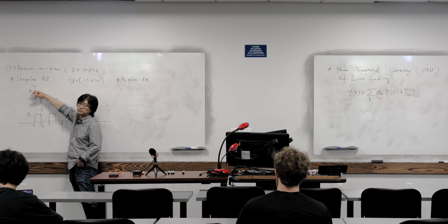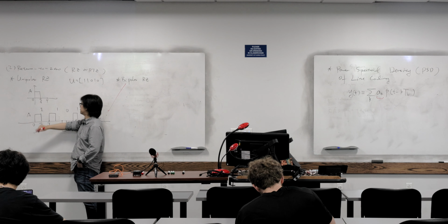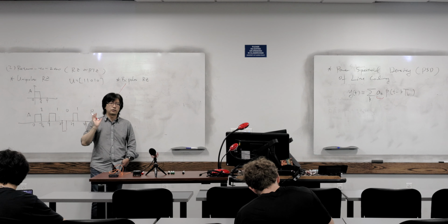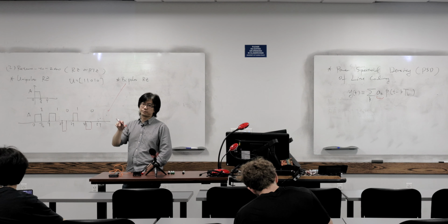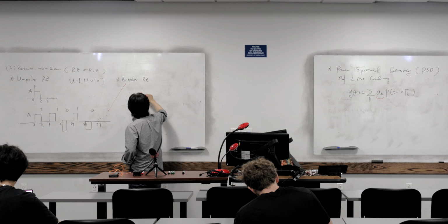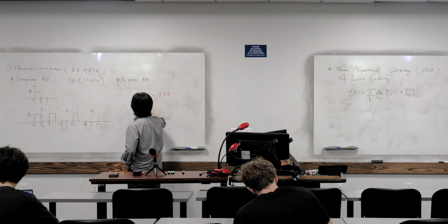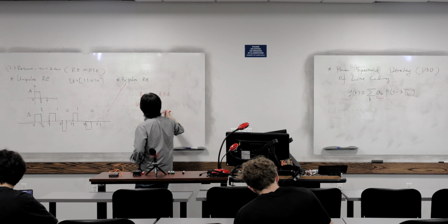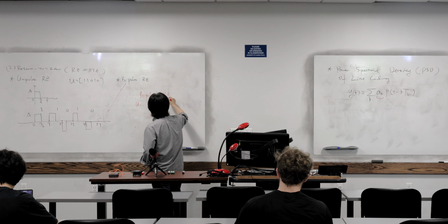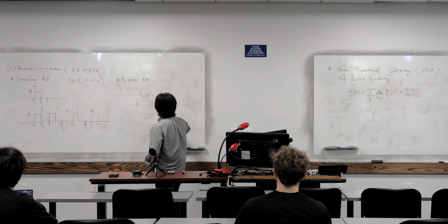It's the magnitude, what we multiply on this pulse. For example, for bipolar NRZ, let's say U is 0 and 1, and A is -1 and 1. We map 0 to -1 and 1 to just 1.